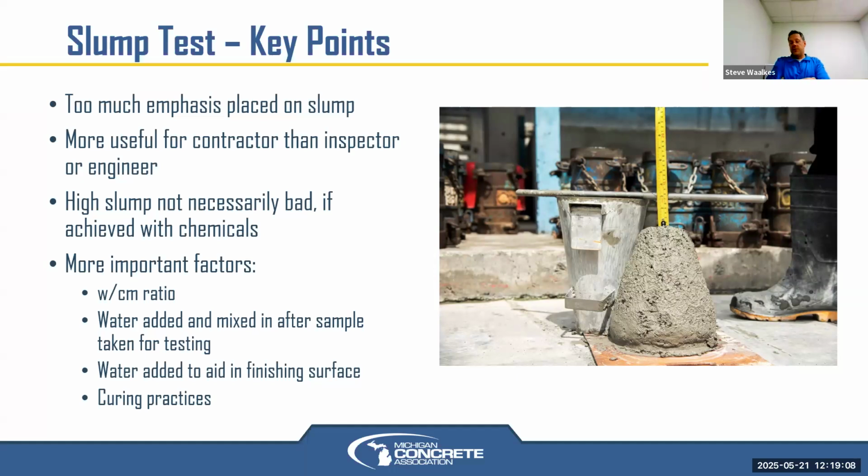We've heard of contractors wanting to add a lot of water to aid in finishing the surface, especially these newer mixes in the last couple of years that are more thirsty, have higher water demand, and slower bleed rates of water to the surface after it's placed. The surface looks dry, and it is dry, and they want to add water. That's good and bad. It's elevating the water cement ratio and weakening the surface. But if you don't add water, you'll have unhydrated cement. So which one's worse?